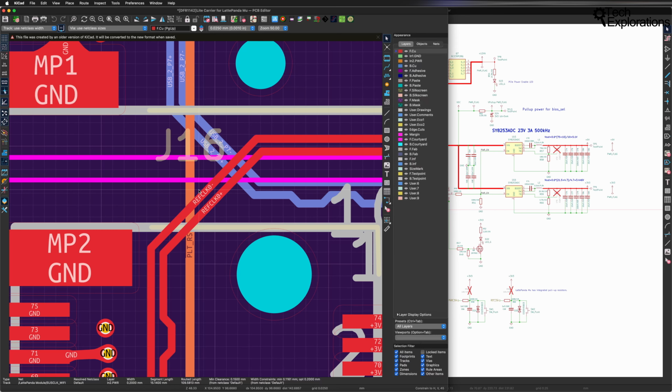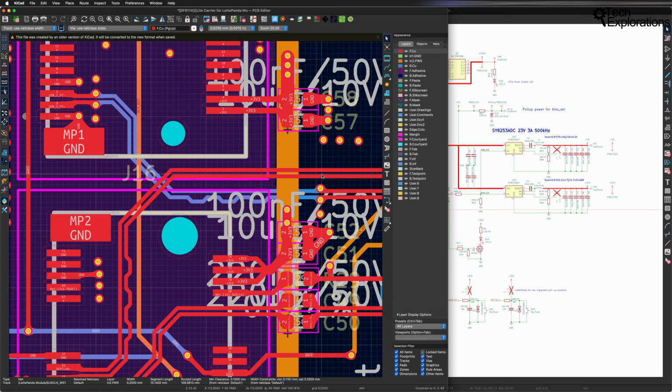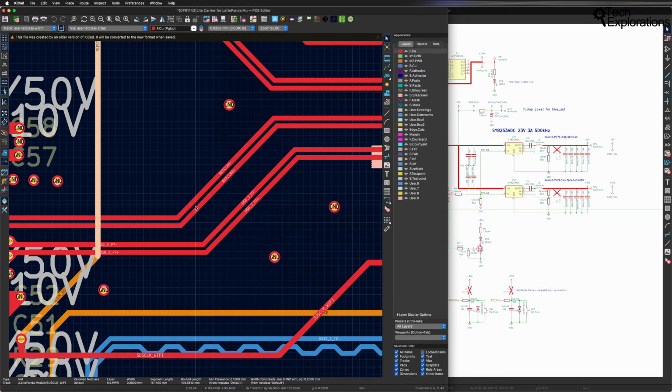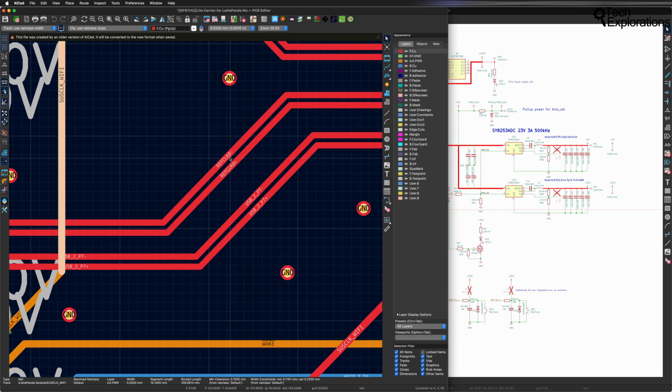I use those two words interchangeably, so tracks, and then also how close those differential pairs are to other differential pairs. You can see here two differential pairs together. This distance between the two is calculated, and there's got to be a minimum distance between them to avoid corruption caused from phenomena such as crosstalk, for example.